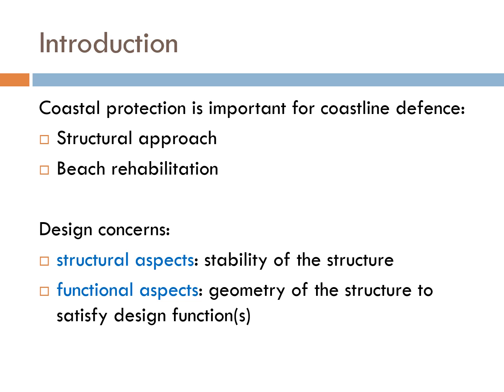There are two approaches. One is the structural approach, which involves the construction of hard structures, and the other one is beach rehabilitation, which is a soft approach. In terms of design considerations, there are two aspects. One is the structural aspects, which look into the stability of the structures, and the second one is the functional aspects, which look into the geometry of the structure to satisfy the design functions.